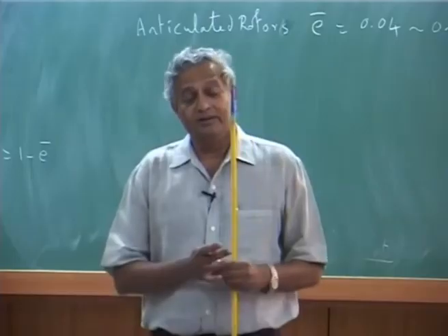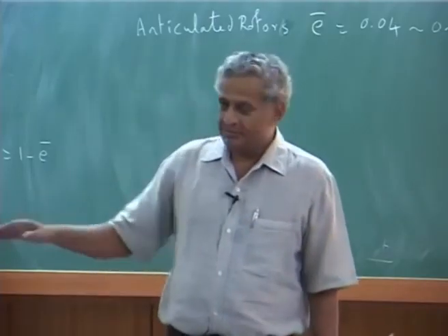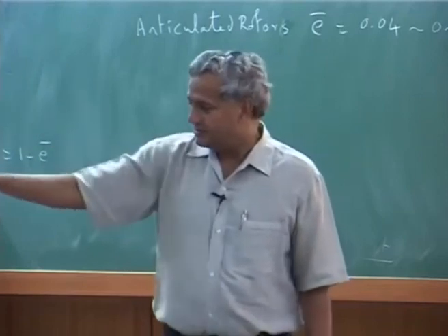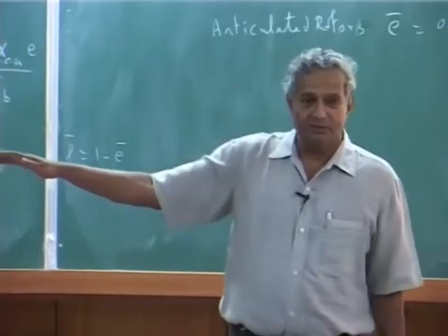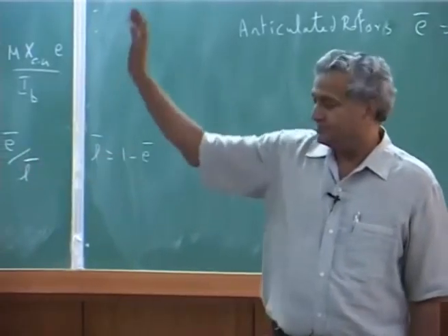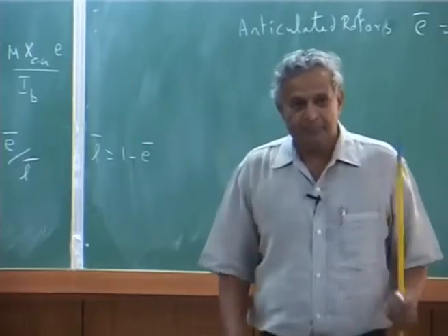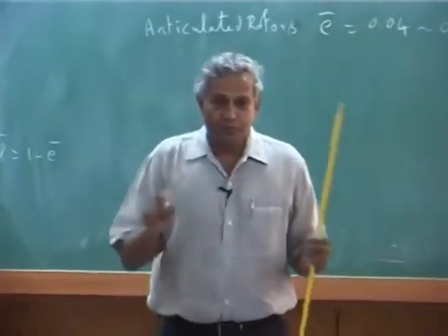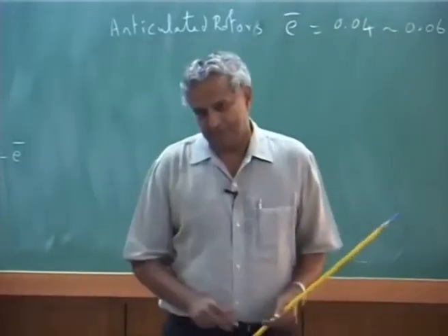You do not face that kind of an instability in the fixed wing, because in fixed wing you do not have this bending, only you take torsion and bending, out of plane bending. Here two bending motions can make the blade unstable. Okay.